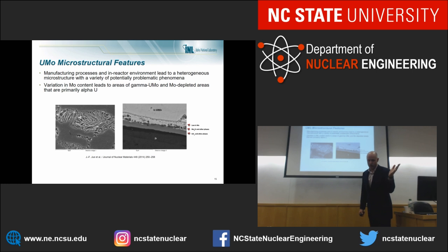I mentioned before that this shouldn't matter because in reactor it goes back to the BCC phase. However, whenever it changes phase, you're left with networks of dislocations in these systems. You have either twins or grain boundaries that form.